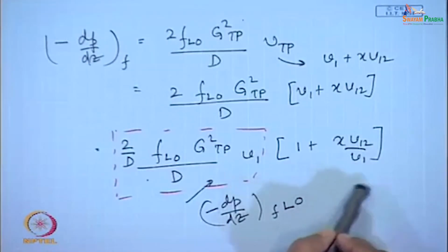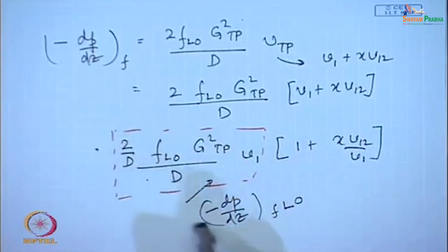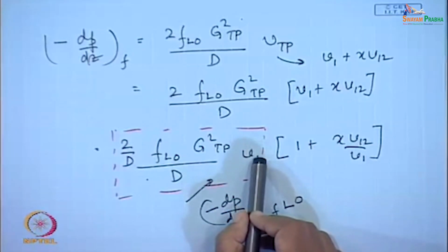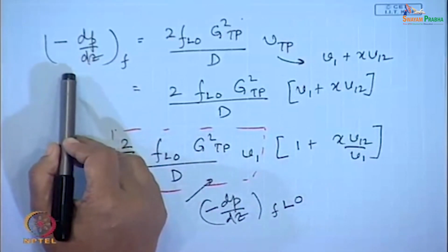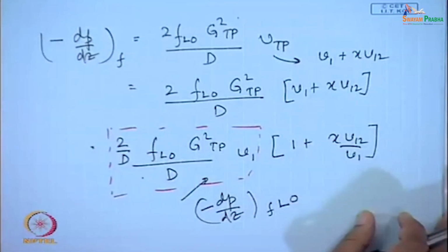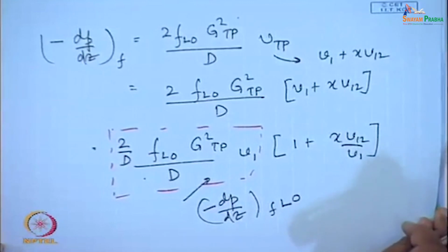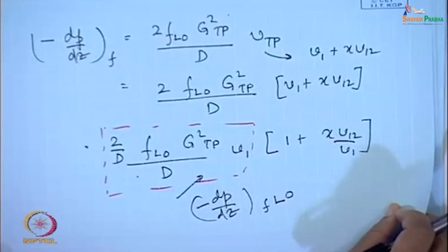Specific volume is nothing but the physical properties. So, we can incorporate a suitable correction factor to the expression of the single phase liquid flow only pressure gradient, and we can obtain the pressure gradient for the two phase flow situation. Clear to all of you? This is when we were dealing with low quality vapor liquid flows.